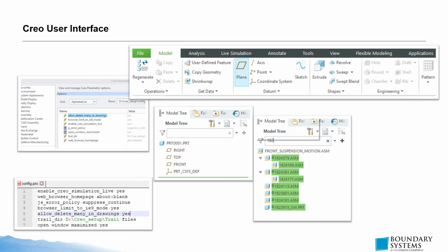So there's still a few functions in the config.pro that we can set, but I think over the last few years, since PDSVISION moved over from Wildfire to Creo, they started using the options tab a little bit more. Essentially what your options tab is doing is putting config.pro settings on and off without you going and looking for them and changing them.